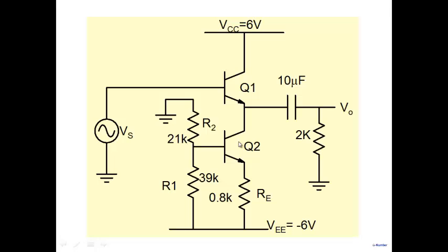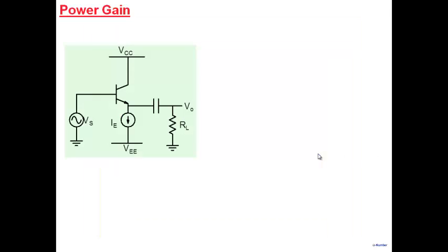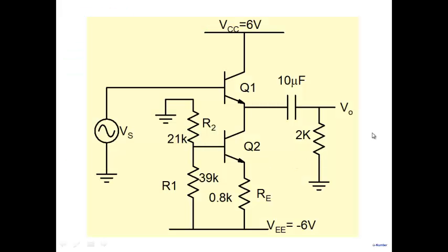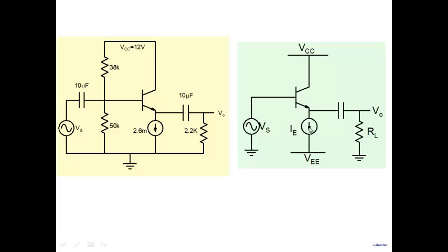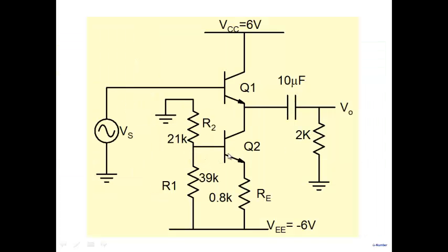It will give you a very high input resistance here. When you look into this particular node, you'll see a resistance which is beta times 2K, so you'll get 200 kilo ohm kind of a resistance. So from the point of view of biasing and getting a large swing, this is the preferred mechanism, a constant current source, and one can implement it in this manner.